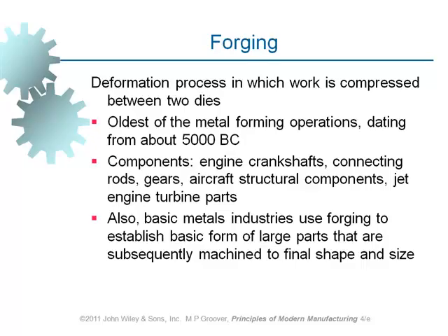They fail after some time because we've got cyclic load being applied as impacts all of the time. The crankshaft rotates at thousands of RPM. And in each rotation, it is being subjected to 2 or 4 really strong impacts. What material can withstand such a harsh working environment? A material which has been forged.